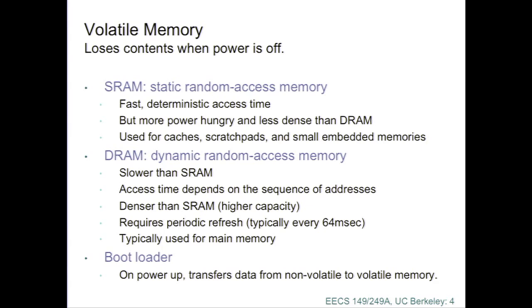The processor clock starts, and something's got to happen. If the clock is running on the processor, then the program counter is getting incremented, and memory is being fetched at the address specified by the program counter. So you turn on power, and the processor runs. It'll be clocking, fetching whatever is in the program counter, which is a register, and executing it. So how do you get a processor started?